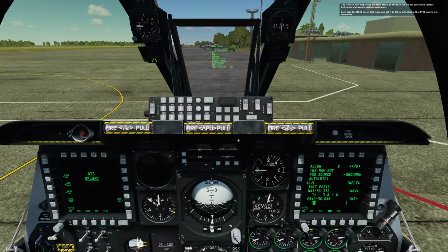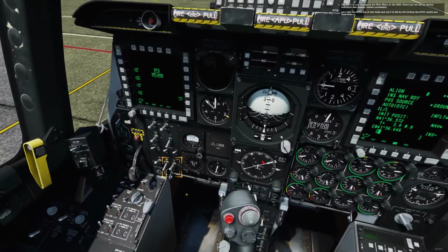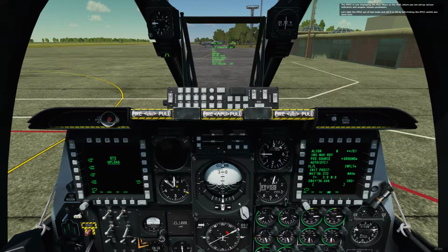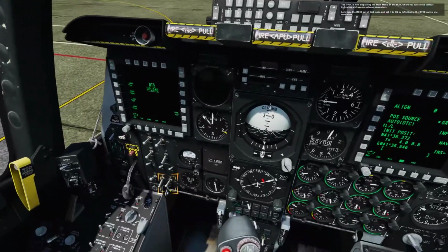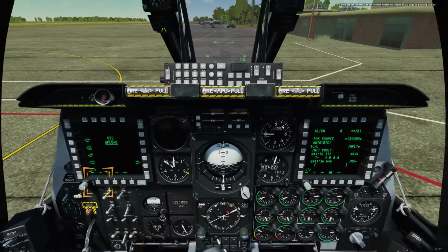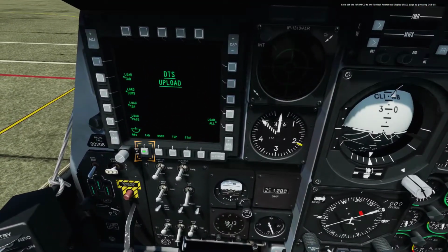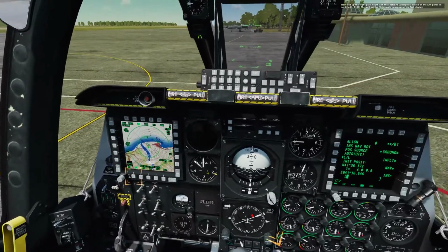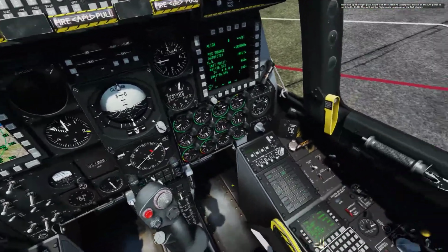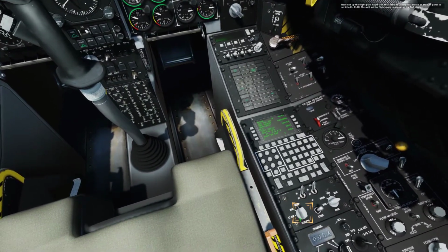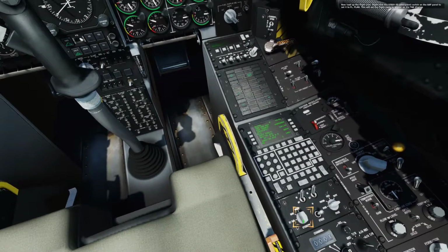The IFFCC is now displaying the main menu on the HUD, where you can set up various indication and weapon release parameters. Let's take the IFFCC out of test mode and set it to on by left-clicking the IFFCC switch one more time. Let's set the left MFCD to the Tactical Awareness Display, TAD, page by pressing OSB 15. Now load up the flight plan. Right-click the steer point switch on the AAP panel to set it to flight plan. This will set the flight route to appear on the TAD display.